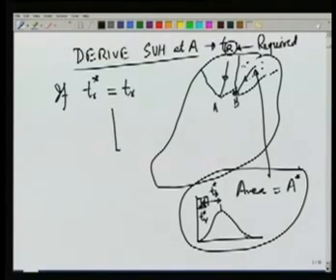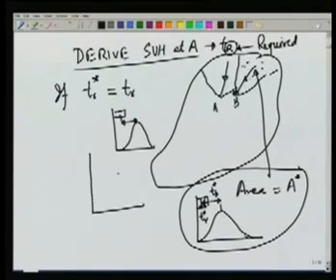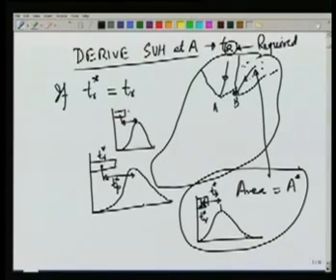So if for a standard duration there is some time to peak, and if there is another rainfall which is not of a standard duration, let's say this is longer than a standard duration, then the peak will shift to the right, and the distance to peak, Tp star. So if this is TR and TP, TP star will not be same as TP,